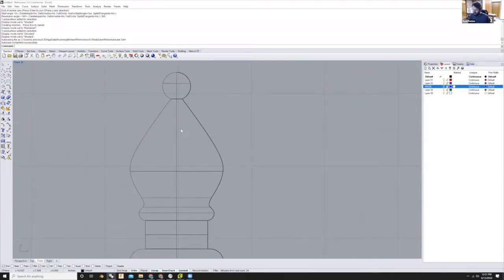And I will draw a line. This line could be on the left or right side, it doesn't matter. I'm currently in ortho mode, and it doesn't let me draw in any direction other than 90 degrees, so in plane. So I want to turn ortho off because I actually want to bring that slice down like that.